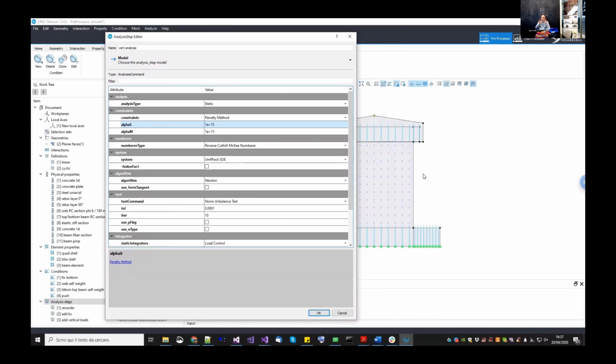In this way, you obtain the maximum number that gives me the best accuracy. Okay. So it is a compromise between enforcing the constraint and keeping a good ratio between the eigenvalues of the stiffness matrix. So remember the order of magnitude of the largest entry on the stiffness matrix plus 8. Okay, so we're fine now.